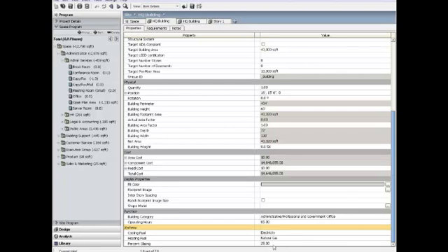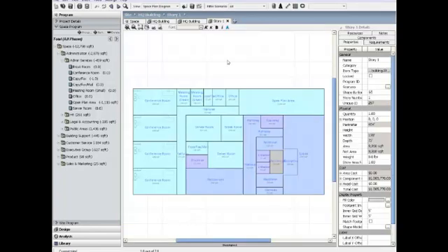Now we can take a look at story 1. You'll be able to see in this story that unlike in the stacked building that we auto-generated, this design shows the room level, and even some details like furniture and objects can be added here as well. To create a design in Affinity, I simply drag and drop items from the space program list into the story view. When I bring the rooms in, they are the correct size and shape, and even reflect color coding that I assigned in the program.